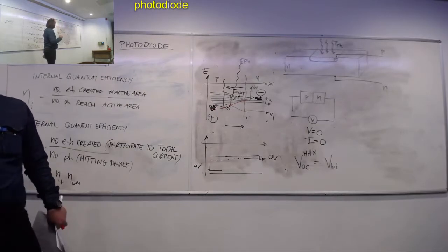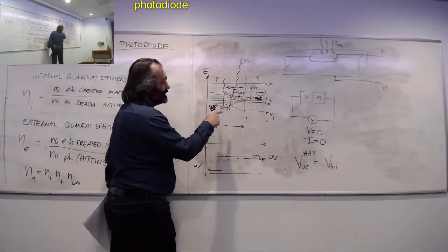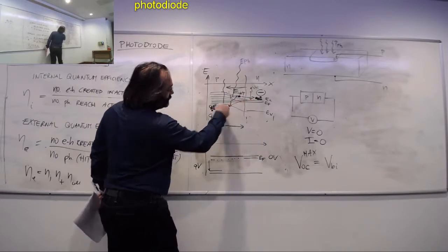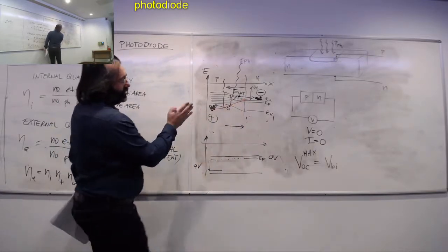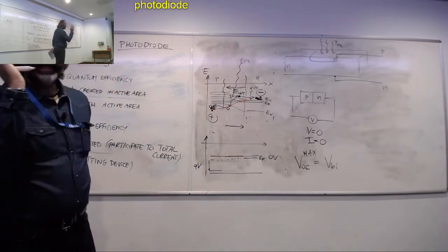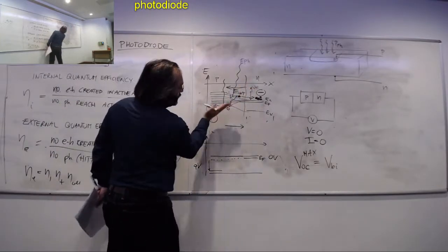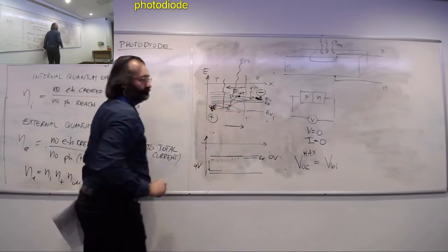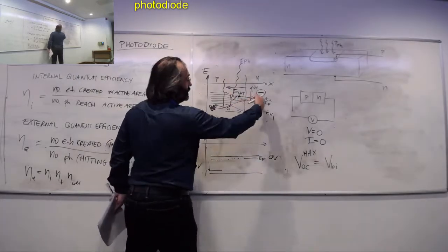This is hypothetical. In this situation, what would happen is that these electrons see in front of them, now that the conduction band has this shape. Remember that the electric field is related to the derivative of the band. So the derivative is positive, the total field now is like that.